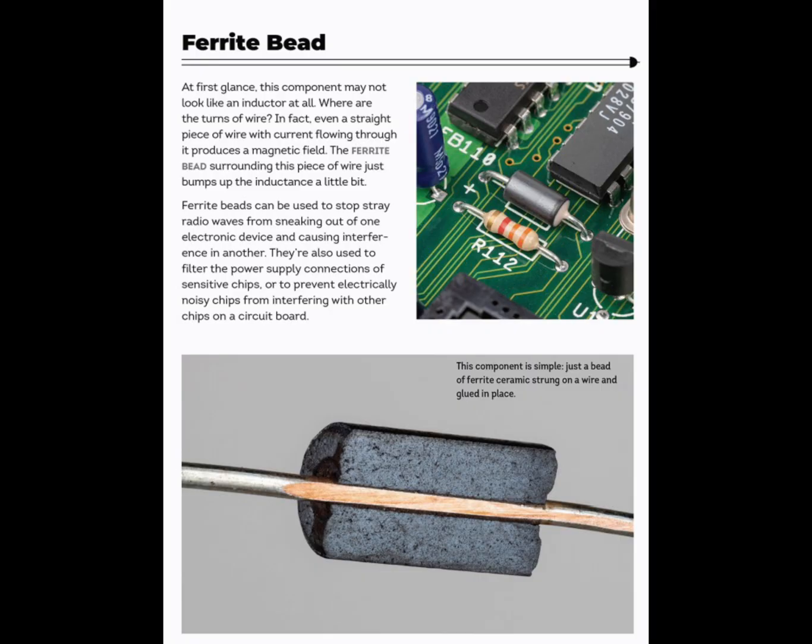They usually are available in surface mount and through-hole designs suitable for various PCB layouts. They are effective at reducing electromagnetic interference and radio frequency interference in circuits. They are small, lightweight, making them ideal for space-constrained designs. They are easy to integrate into existing circuits, typically placed in series with the signal line or across the power supply.